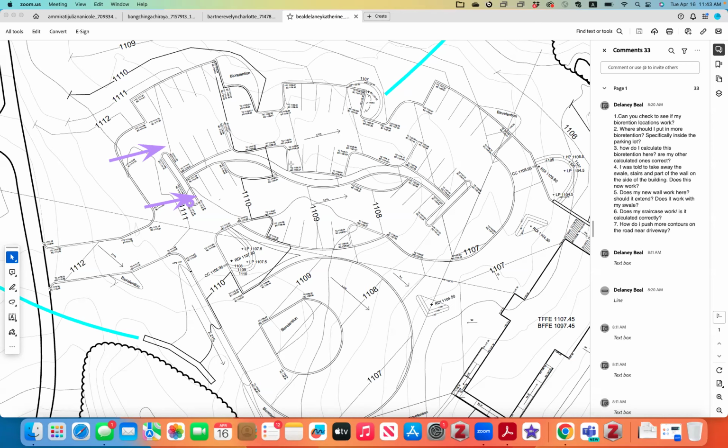For this one, your curb will be your high point. Yeah, you want to specify? Yes. In that case, you would just say TC/HP, because your top of curb is essentially your high point, along the whole curve on the lower side of the curb. So essentially along the lower curb. That's your lower curb. Yeah, that should be your HP there.